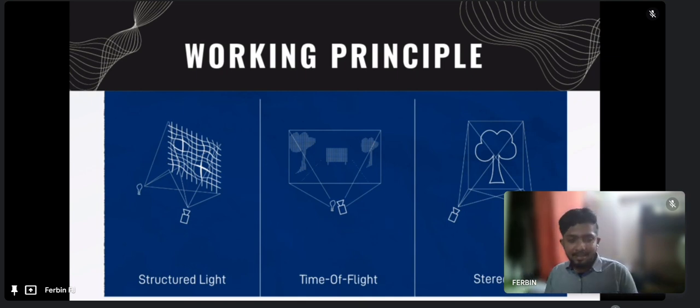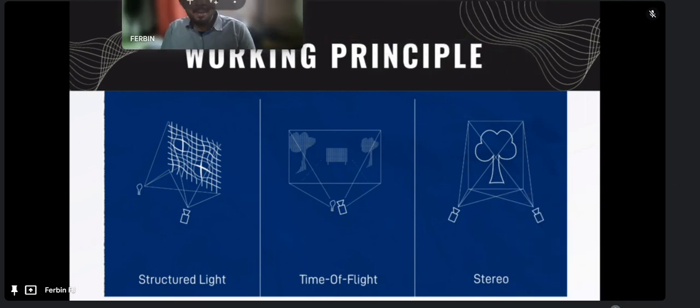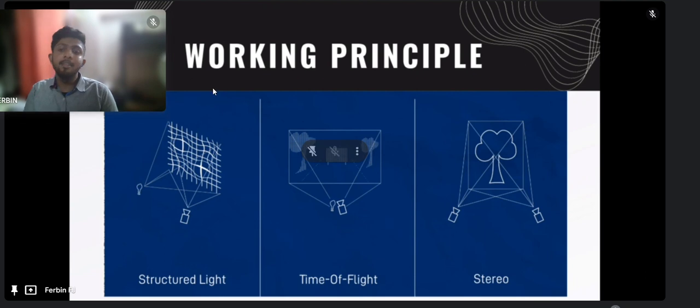The 10 centimeter object will obviously take less time than the 30 centimeter one. Through this variation of time, we can estimate at what location our object is. When you repeatedly take all these values, you get a three-dimensional idea about the environment where we're working.